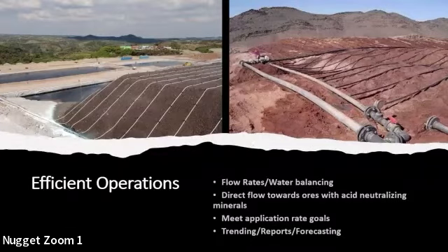We'll take the greater than 2 inch and break it down to 2 inches, because the larger gravel size particles have an impact on the hydraulic performance of the ore, so we maintain that gravel component in there, but break it down to 2 inches. But there are other cases where we would scalp it out and then apply a correction based on the material that's been removed.